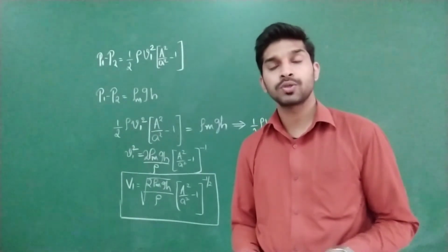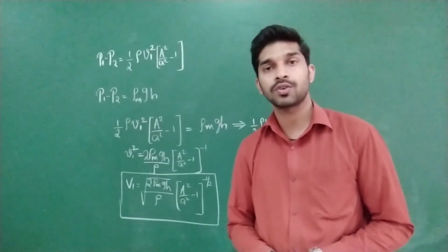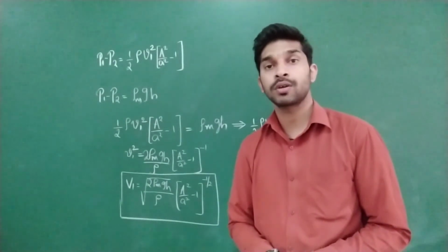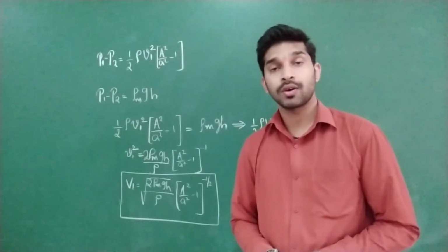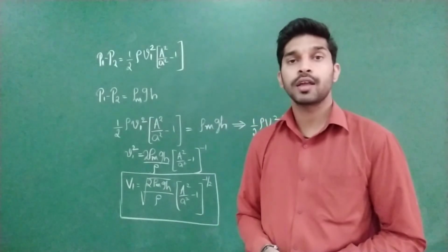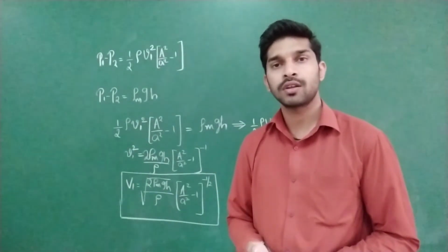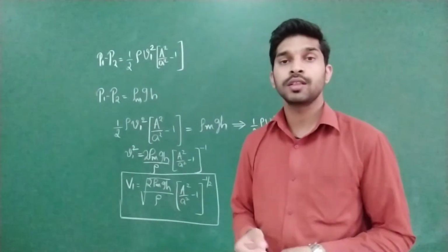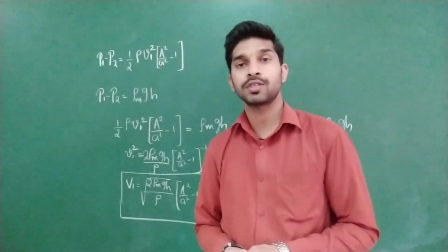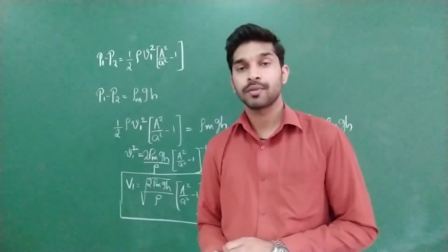Okay. First step you will be going to use equation of continuity. Okay, which is nothing but what? A1 V1 is equal to A2 V2. Next, after that, you will be considering about Bernoulli's principle. Okay, Bernoulli's theorem, that complete definition. Okay, sum of pressure, and kinetic energy per unit volume, okay, potential energy per unit volume, that addition will remain as constant. Okay, in that we will be having two set of equations, actually more than two set of equations, but major equations I had named as equation A and equation B, correct now?